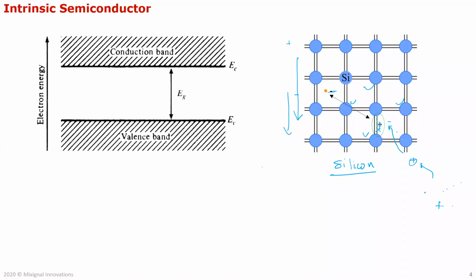So in other words, it looks as if a positive ion is moving in this direction if I apply the same electric field. Electron moves this way, positive moves this way. Because in an intrinsic semiconductor they're exactly the same, a lot of them recombine, so you don't get a lot of conduction current. That's an intrinsic semiconductor.